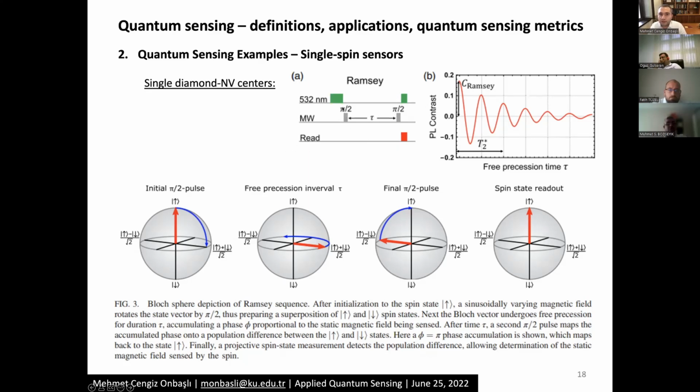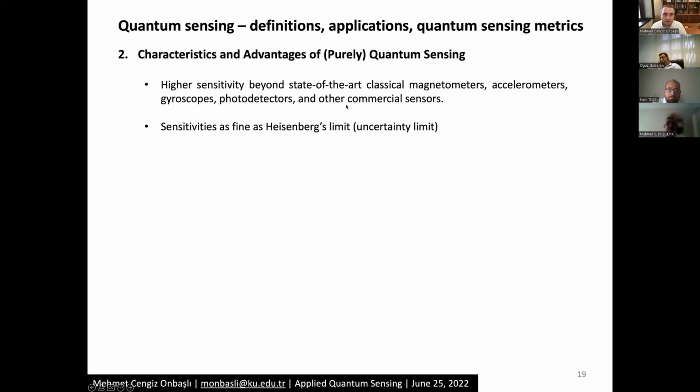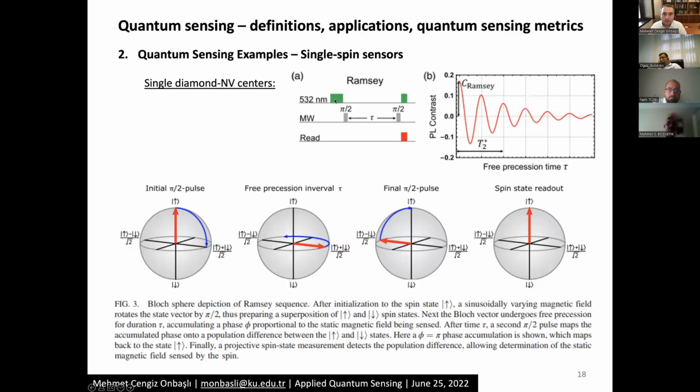So these are essentially state preparation, relaxation, and readout steps. These steps are going to be relevant for the way they decay and what frequencies we get and how fast they decay. So these are the important readings, especially from the photoluminescence as a function of time for our sensor chips. What we do in this kind of a system is we first excite with 532 nanometers, which is the green laser as I showed you previously. And then we set our state to up orientation, as you will.